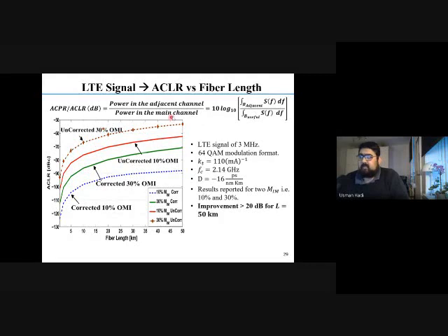So if you see that we are at a very high power of -50, -60 dBc here, and with the performance correction that we have done, we are around -90. So in the negative scale, you see that we are actually suppressing the leakages in the system.